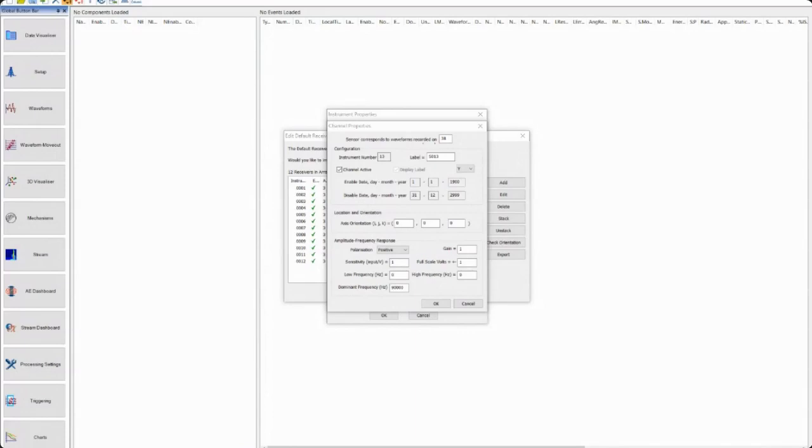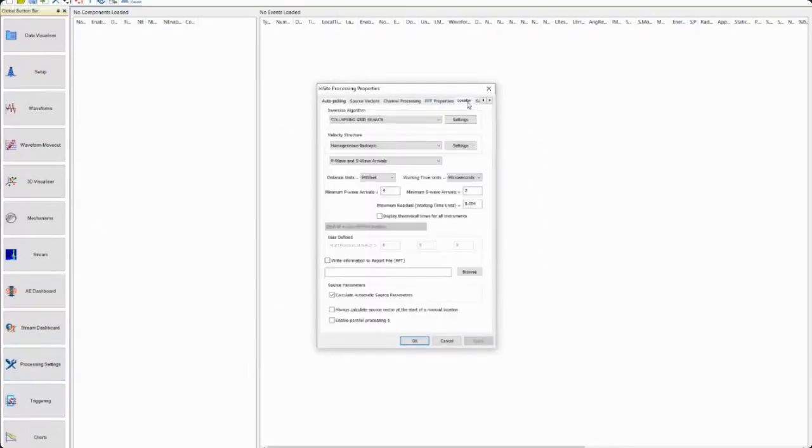What kind of velocity model do we use in grid search? Also, do you use any ray tracing algorithm? Yes, thank you, Bulent. In InSite-Lite, as I said, it's limited in the number of options that we have. So basically, grid search will take any velocity model, up to 3-dimensional voxel models. It will take layer models, isotropic layer models and anisotropic layer models. And yes, it does ray trace.